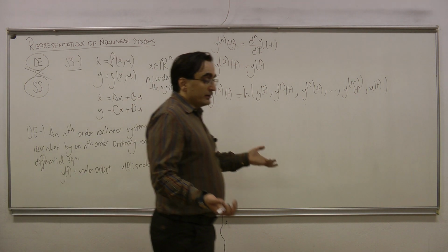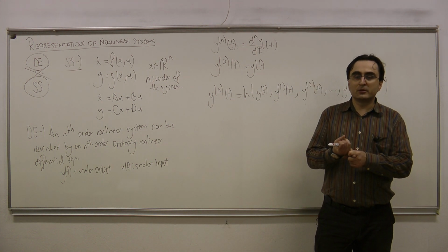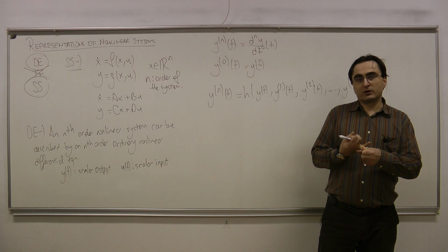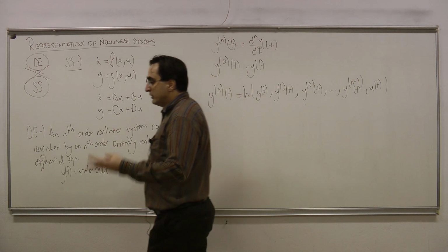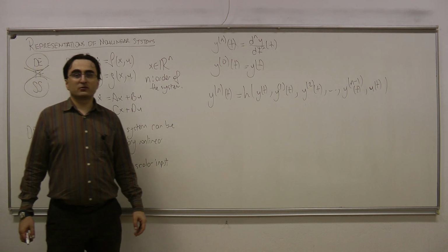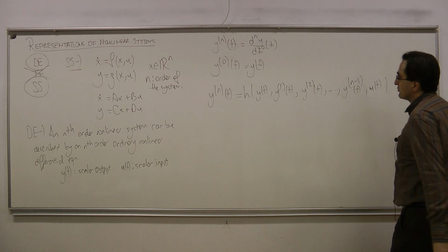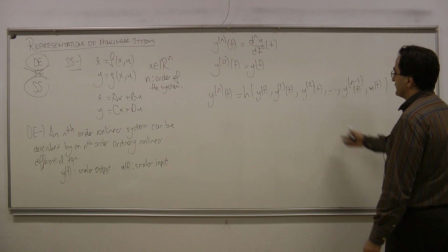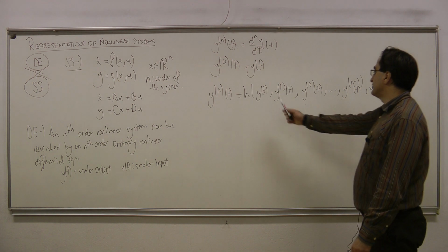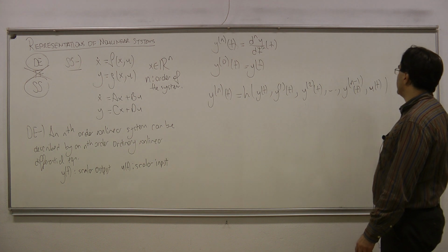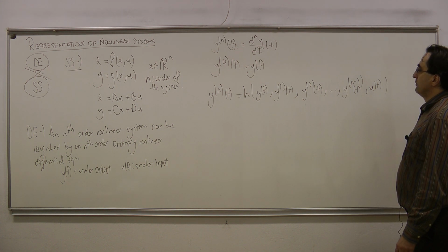Remember, in linear systems, for a single transfer function, we can find controllable canonical form, observable canonical form, or diagonal canonical form type of representations. These are only 3 of the infinitely many possible ones. Okay? Here we are going to choose a very, very specific state space representation for such a nonlinear differential equation. Here this h is in general a nonlinear function of these arguments.